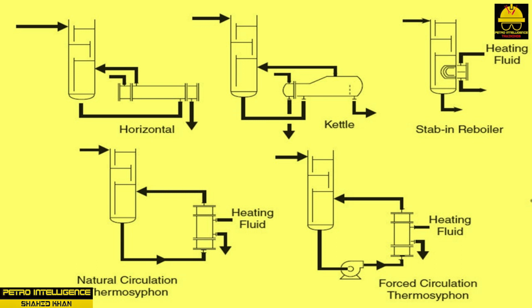Reboiler or steam injection. Reboilers help control overlap and heat balance. Several types and arrangements of reboilers can be used on a distillation column, as shown in the picture. Kettle reboilers draw feed from the bottom section of the column by gravity flow. An internal weir holds a liquid level over a heated tubular bundle. A vapor disengaging space above the tubular bundle allows the liquid to boil and roll freely and enrich the void with vapors. As the lighter components break free from the larger, heavier molecules, they rise into the vapor disengaging area and exit the top of the reboiler.